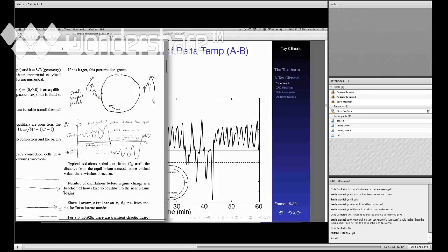That's what this arrow is meant to represent. So this tiny little pocket is a little buoyant compared to what it was last time around the loop, and it accelerates the fluid. Okay, so this little warm pocket is now traveling through the cool section warmer than it was last time.